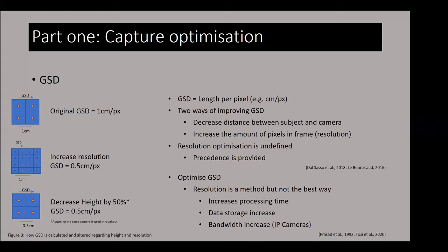Sometimes zoom lenses can be used to increase the focal length of the camera, which can have the same sort of impact. One thing to quickly note here, however, is the possibility of the stage increasing in the rivers with fixed cameras. A large increase in stage can actually hinder the viewpoint of the camera if it's too low down with a narrow angle, because it will just shrink down the area that the camera can actually see.